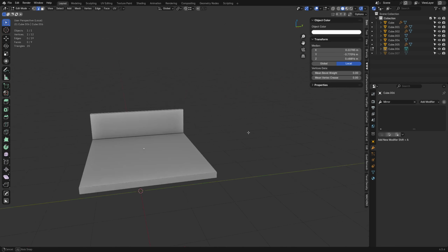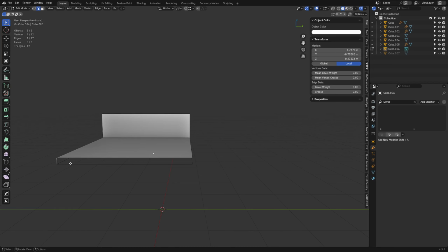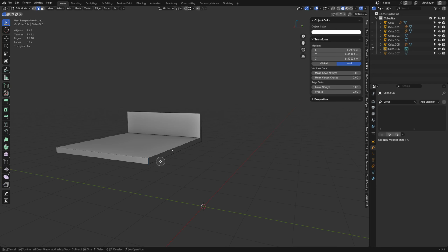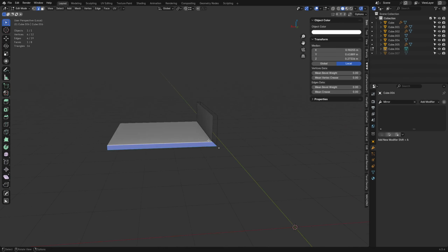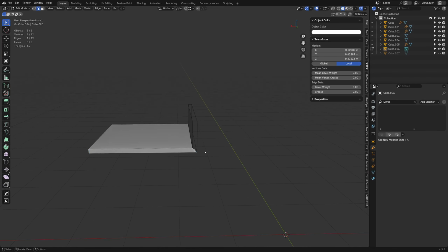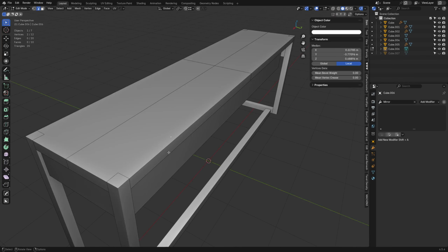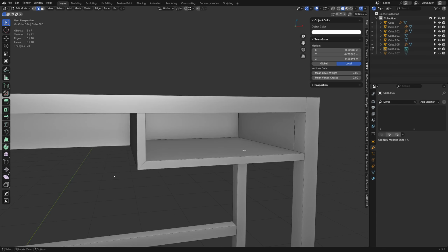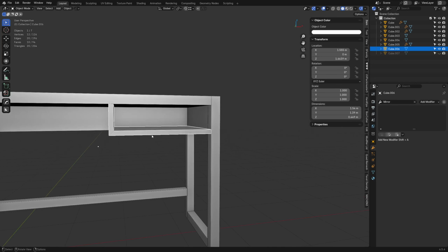So we're just going to grab those, by the way, kind of skipping ahead. You can grab one edge. If there's two parallel edges going to a single vertex out here, you can press F. Usually it will fill it. Otherwise, you can select multiples and hit F. You can do that as well. In our case, we could have done the whole thing with the one edge because they're all parallel. They're all quads. You could do F, F, F, F all the way around. So it's a really cool way of filling those little borders if you need them. And that's it. So we got that going.